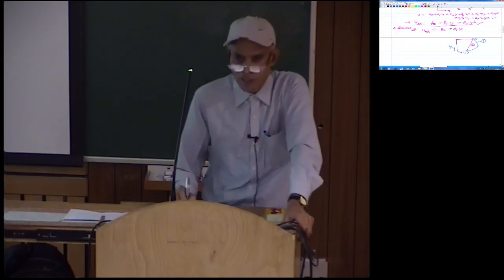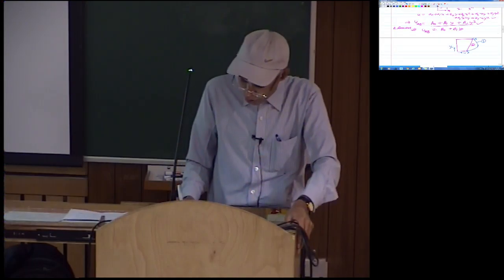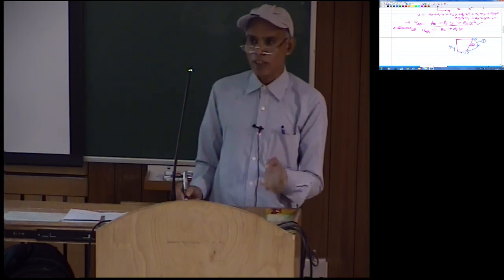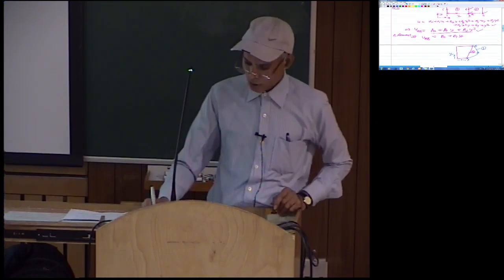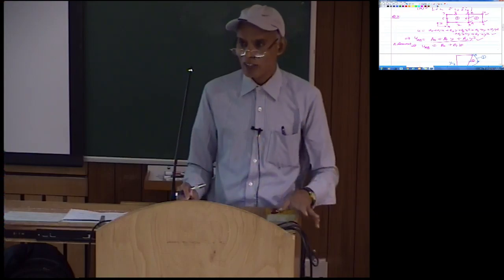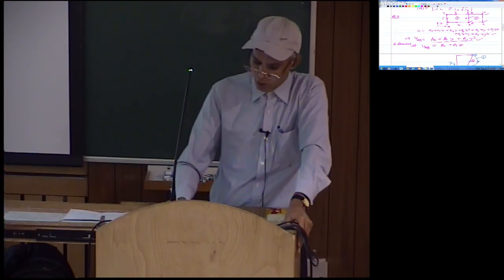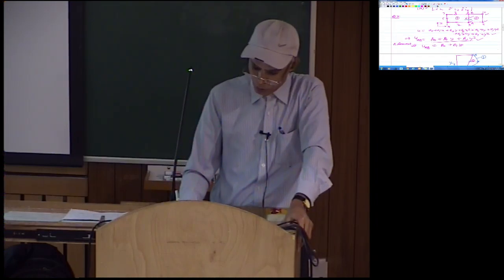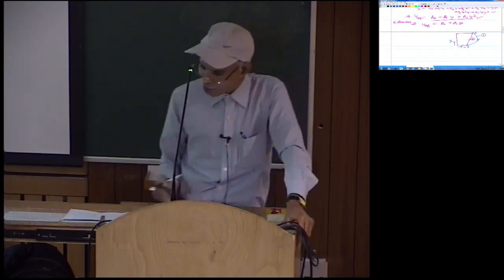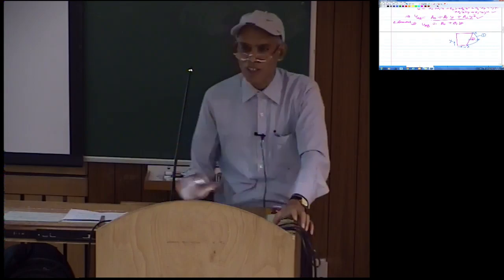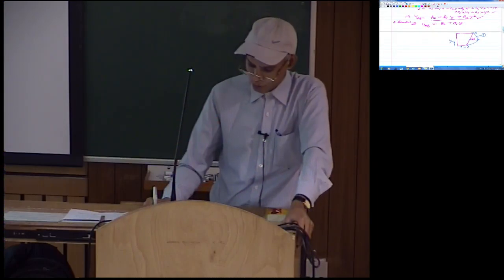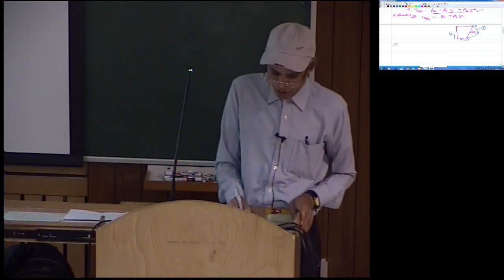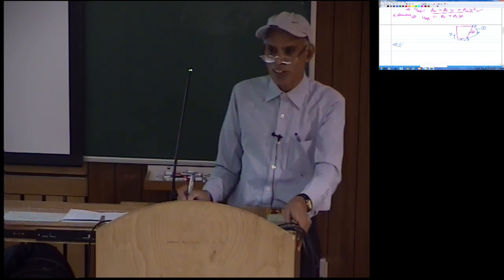of course a general case, what we are talking about, a general case. So in between, element 2 is giving some value of u, whereas element 1 is giving a different value of u. So there is no continuity of u across the element when we go from element 1 to 2. So it's an incompatible displacement. These 2 elements are going to be incompatible, and will not give a continuous displacement distribution when we go across this edge. So this is what I wanted you to discuss, and of course we had discussed the continuity requirements, considering different elements. I think the question number 4 is a straightforward extension of what we had discussed as heat transfer problems.